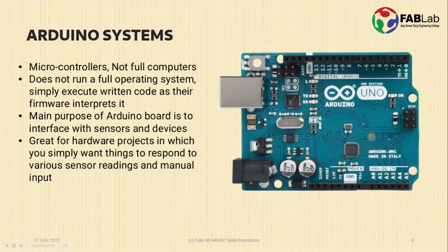These are a few capacitors, and this is the voltage regulator IC, so that you may get 5 volt as well as 3.3 volt from this Arduino Uno board. And the important thing is this, again one more Atmel IC on the board. This IC is again a powerful microcontroller, which is dedicated to performing the task of programming.